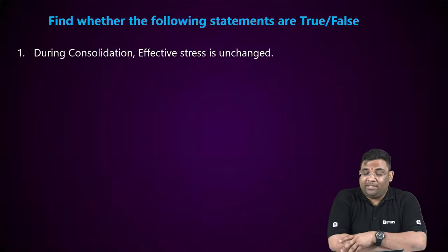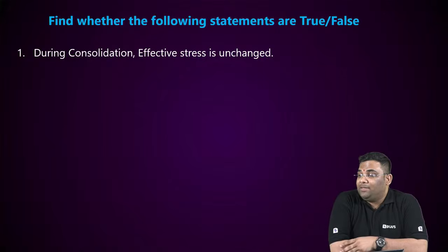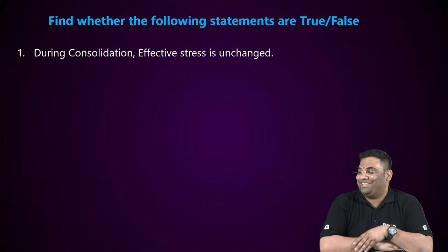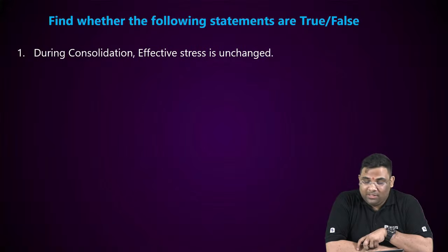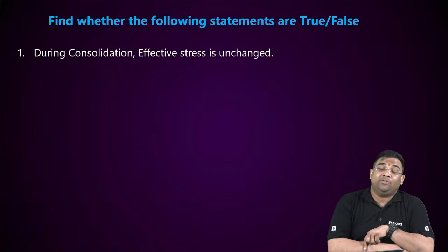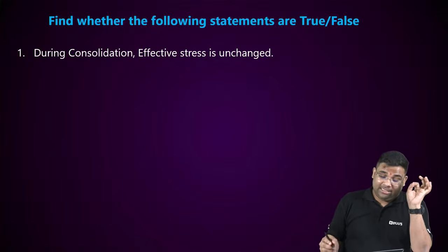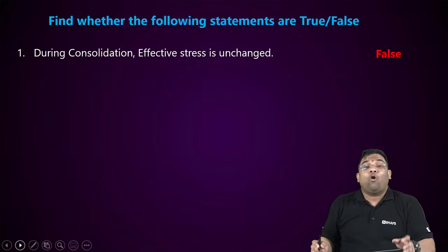During consolidation, effective stress is unchanged. Please write T or F, or true or false. Don't write yes, no, I'll get confused. Okay, true or false. So many confusions. Effective stress changes. So this statement is false.